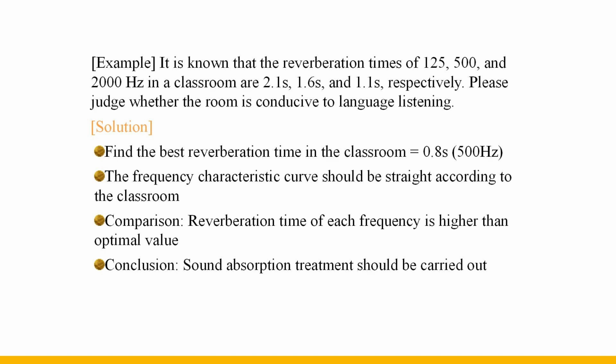Since the classroom is dominated by language and intelligibility needs to be considered, the reverberation time of low frequencies should not be higher than that of mid frequencies. The frequency characteristic diagram of the optimal reverberation time should be flat. That is, the optimal reverberation time at the three frequency bands should be 0.8 seconds.